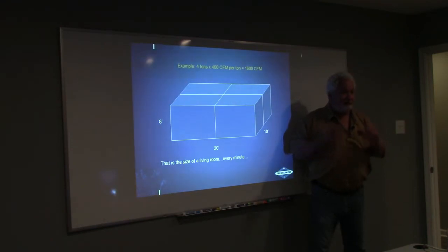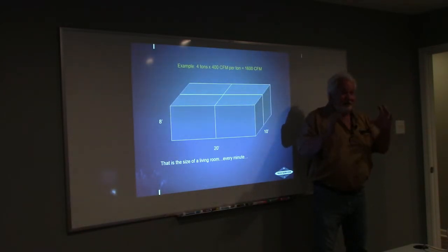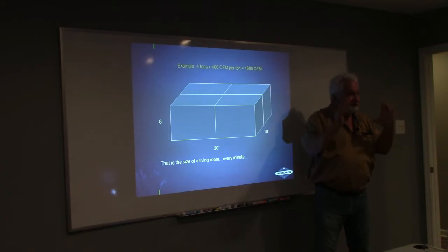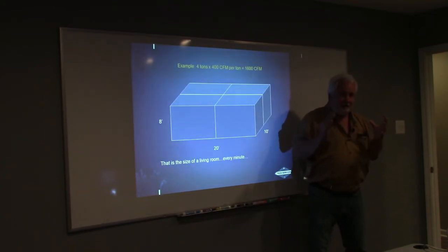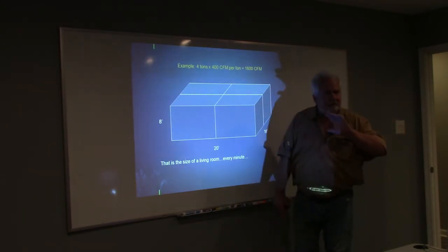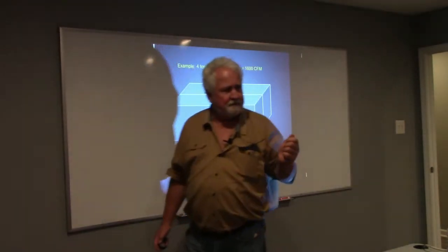Now tell me this, can I do that through an 18-inch duct? Stop and think about it. It's like making boudin this big. You can't get this much air through this size duct. It's physically impossible. Do you get that? So that's what I'm talking about with cubic feet of air. We have a volume of air that needs to move through that duct. And just because it's moving through doesn't mean it's moving through effectively. Everybody cool with that? Good.